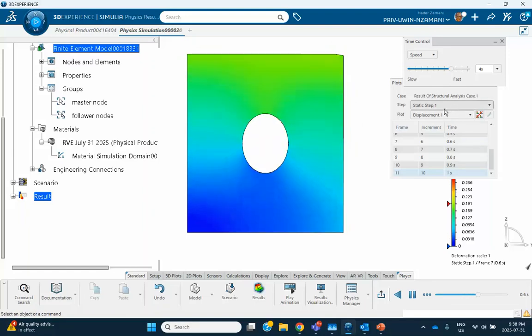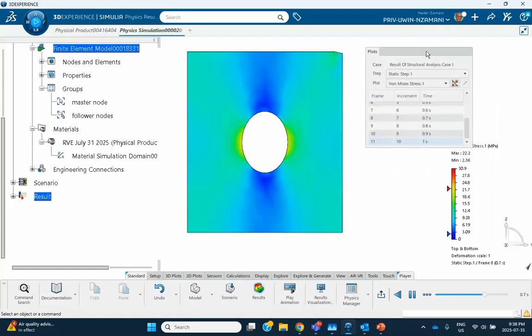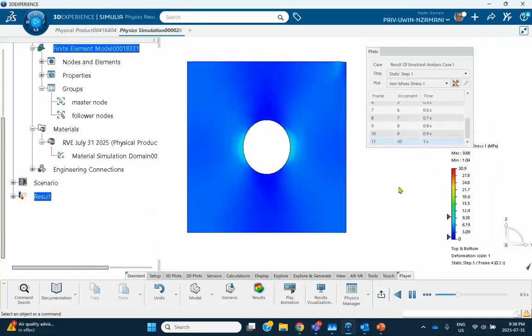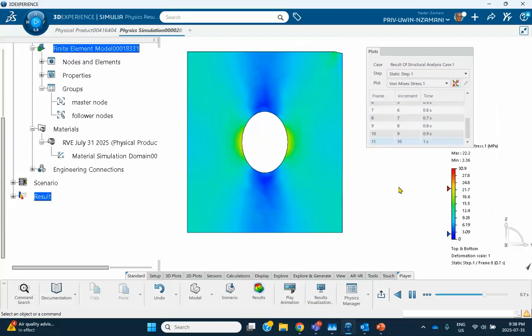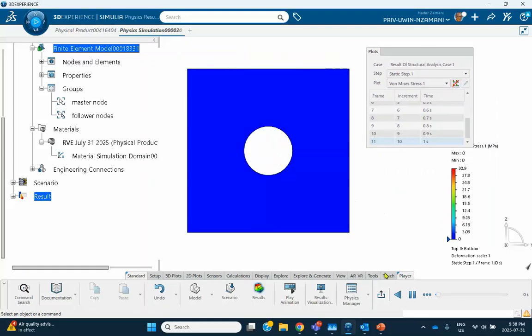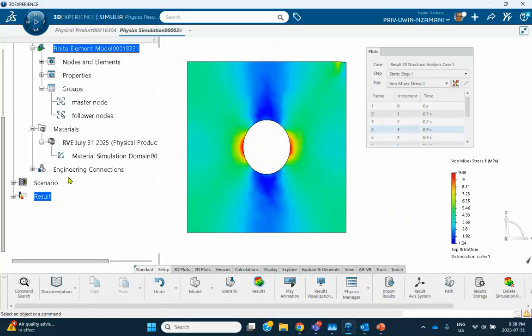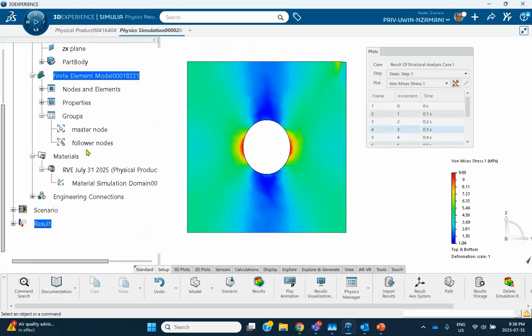And incidentally, if you look at the von Mises stress, you get around 30, which is very close to what the fellow gets using Abaqus. The intention here is not to compare or decide on accuracy. We just want to know how to do that. Now, let me exit this and go ahead and take that coupling away, so you can either take it completely away, or let's do that.